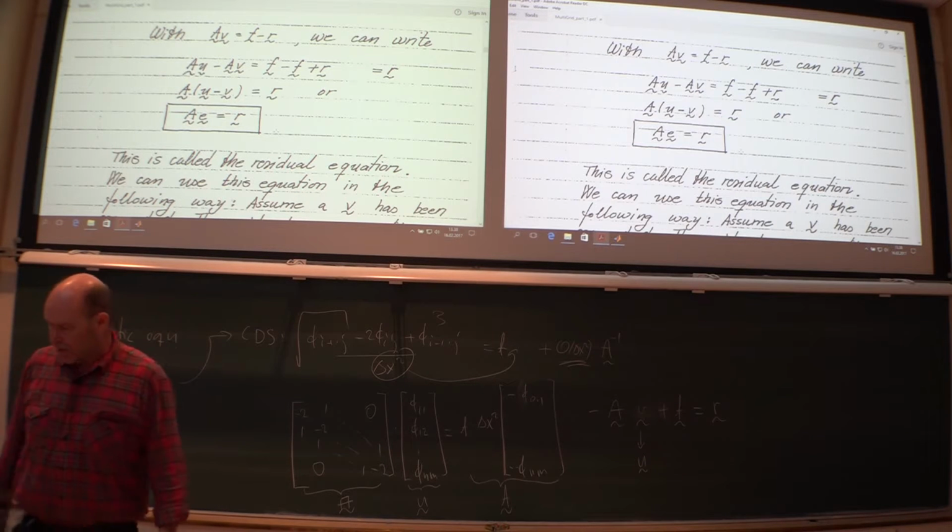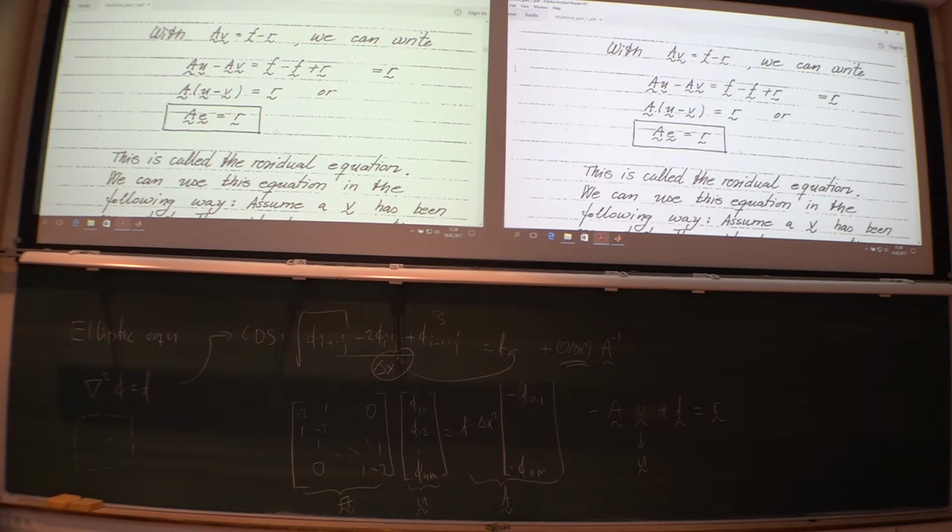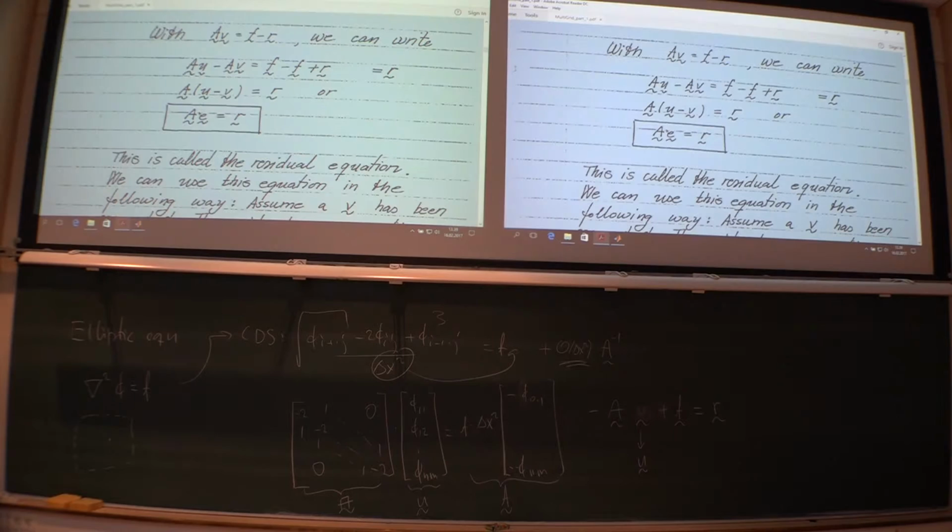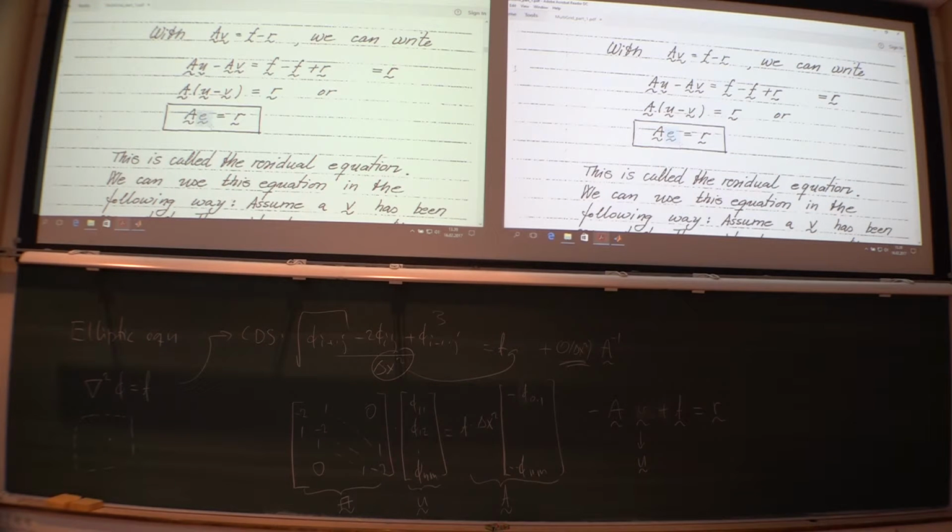And the reason is that on a coarse mesh system, we have to transfer whatever we have as the unknowns down to the coarse mesh. They will turn up in the residual. So first you start calculating the residual on the fine mesh. Then it is the residual you push down as a new right-hand side of your equation system on the coarse mesh. And then we are trying to find the error on the coarse mesh.